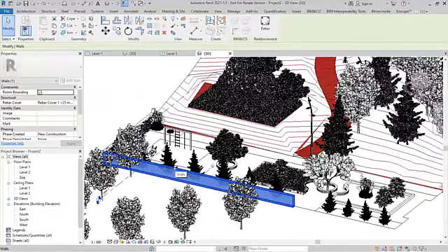And if you want a different shape, if you have any 3D geometry in Rhino, you can also transfer that as a direct shape to Revit and tag it with a specific type according to Revit. So you can type any direct shape as a wall. Or you can extract the path curve of that object and have it as that wall path in Revit. In that case, Lands Design can identify the path curve of this wall, the height and the thickness, and generate a geometry that is transferred into Revit as a wall.